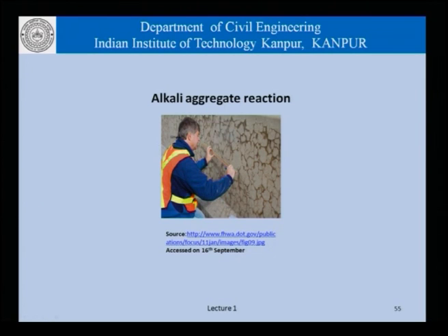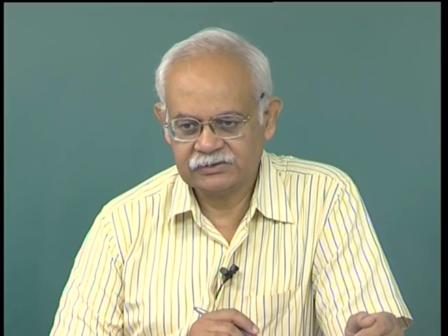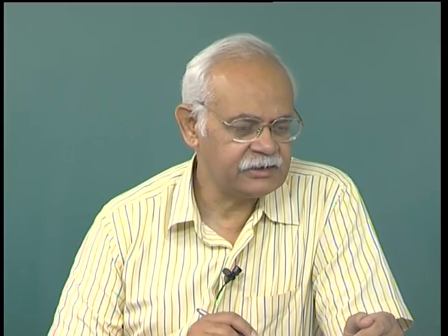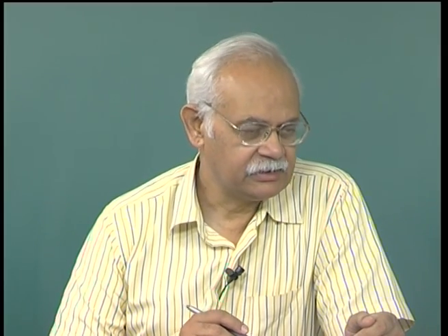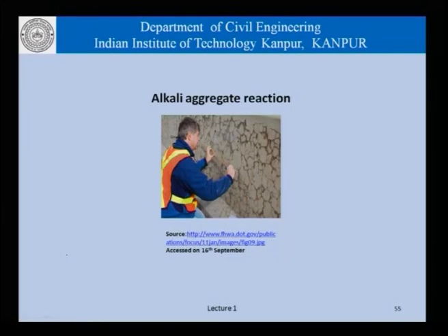We said in the beginning of the discussion today that aggregates are all inert fillers. That is true in the normal sense of the word, where normal aggregates and normal cements are being used. Some aggregates, however, have been found to be reactive. That is, they react with the hydration products of the cement paste, and that causes the concrete to deteriorate, and what we call that is the alkali aggregate reaction.